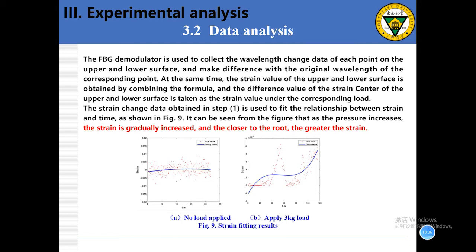At the same time, the strain value of the upper and lower surface is obtained by combining the formula, and the difference value of the strain center of the upper and the lower surface is taken as strain value under the corresponding load. The strain change data obtained in step 1 is used to fit the relationship between strain and time, as shown in Figure 9.